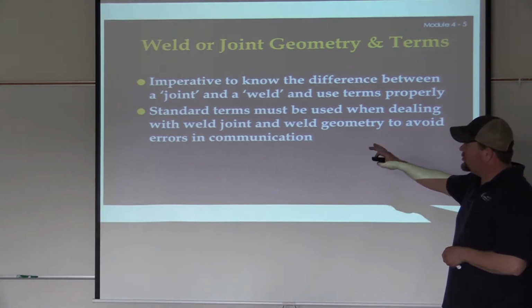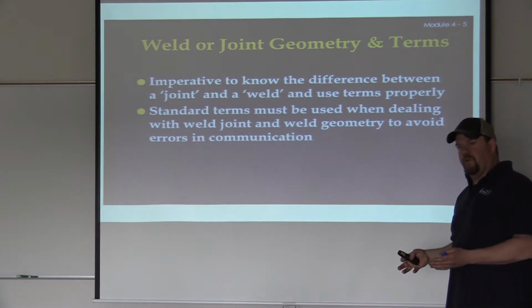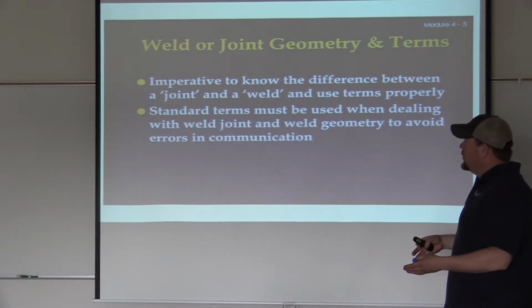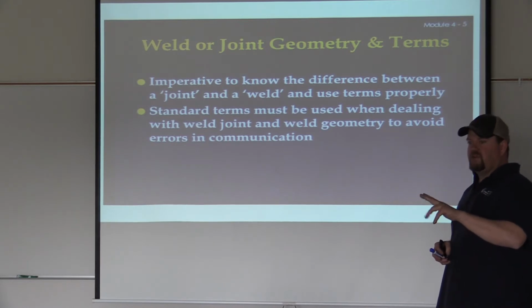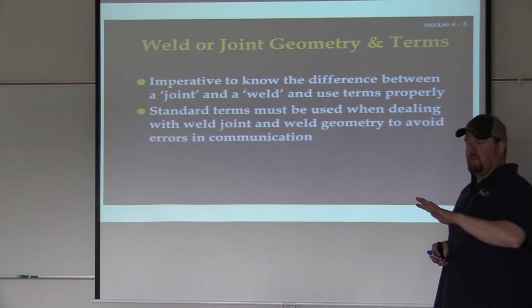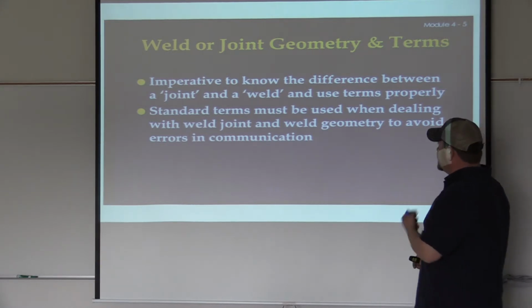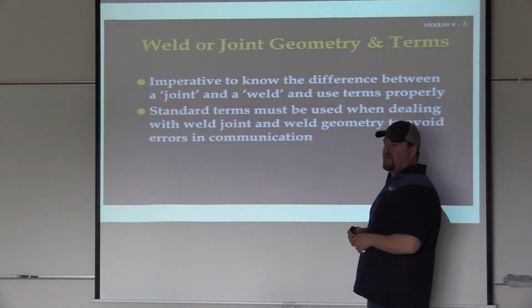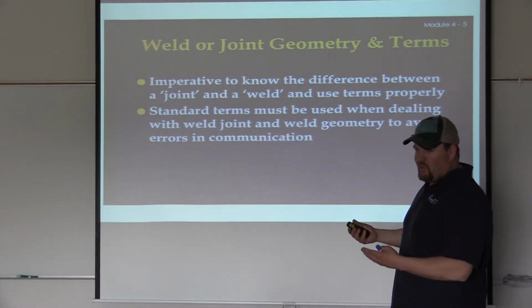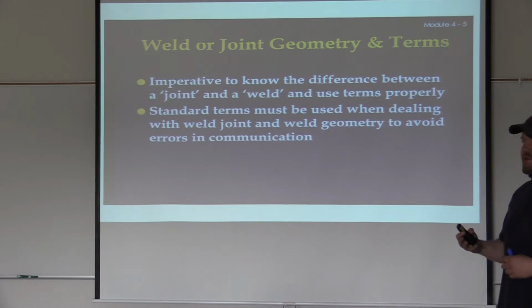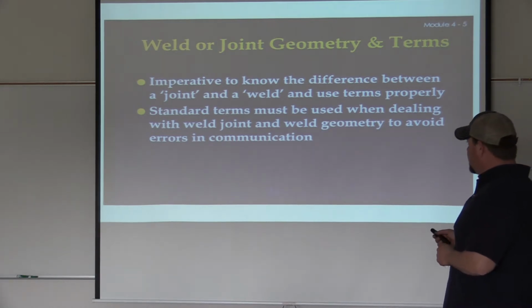So it might be a butt joint, but with a V-groove prep, right? There's only 5 joints. We know that. T, lap, edge, corner, and butt. Correct? Yeah. All right. Everything else is the prep within that, right? So a V-groove weld, that's what we call it. The weld will be a V-groove, but it's actually a butt joint with a V-groove preparation. We fill it up from there forth.